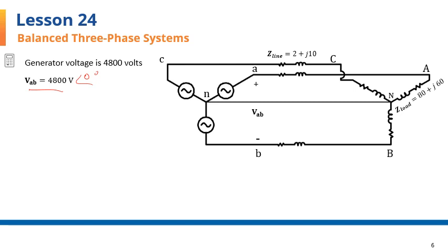The easiest way to analyze a balanced three-phase system that connects a Y-configured generator to a Y-connected load is to draw the equivalent line to neutral diagram of a single phase of the system, find the answers, and then extend the answers to the three-phase system. I've symbolically separated the equivalent line to neutral diagram of the A phase of this system.